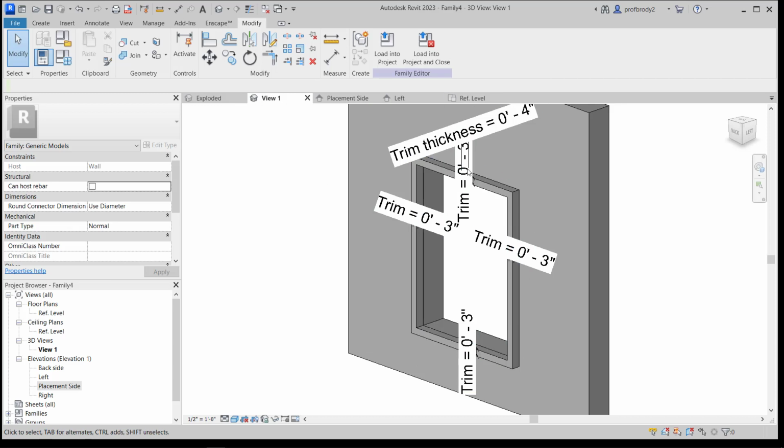And before we have the family talk, it is absolutely possible to add other elements to this. For example, a crown molding. And you can snap and lock the crown molding to the top of this piece of trim so that the crown grows and shrinks as the trim does. And of course, I've just created boring rectangular pieces of trim. You could create all sorts of fun shapes with something like a sweep. This path of the sweep could also be locked to the opening.